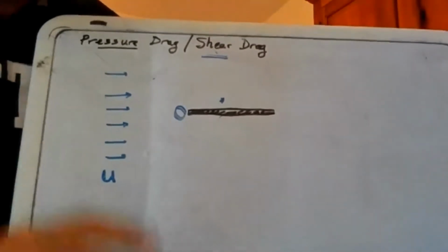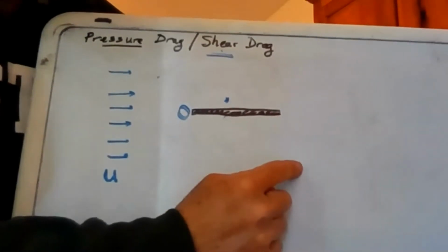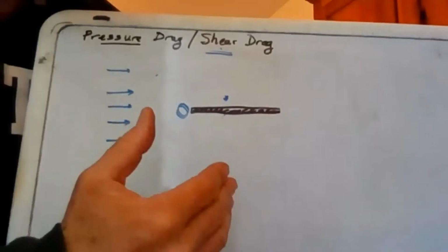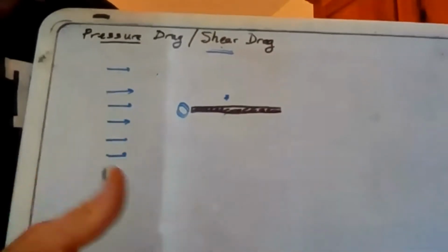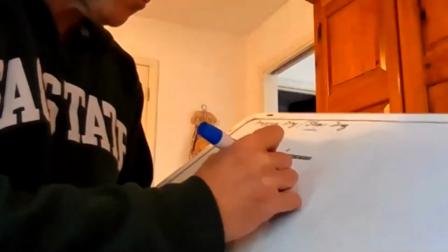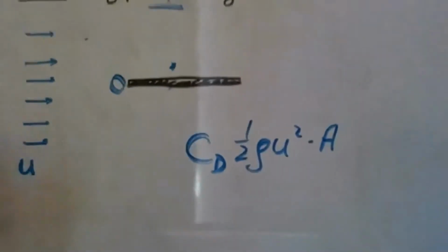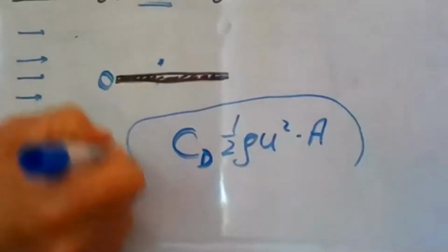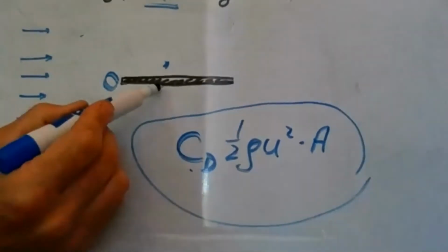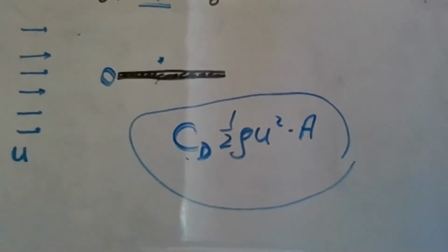As a consequence, our equation, which I won't write out, but we had our drag force is equal to the dynamic pressure, 1/2 rho u squared, times the area. And the idea was that dynamic pressure was becoming drag. Doesn't really apply here. And yet, I'll write it out really quickly. People in fluid dynamics, they like to stick with one equation. So as a consequence, this coefficient of drag really needs to get modified in this case, or in general cases where an object is somewhat streamlined.